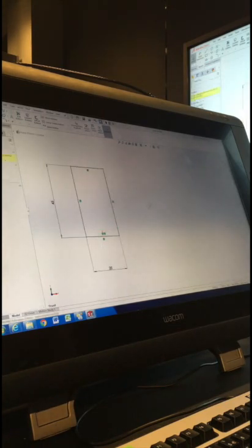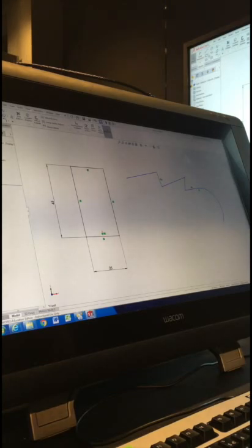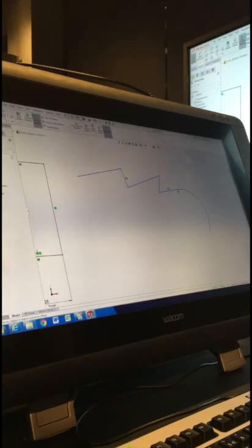Before we do the offset, I'm just going to explain to you how it works. The offset tool is on our sketch tools. See it up here, offset entities. Now by default, it'll be 10 millimeters with add dimensions and select chain turned on. I'm just going to turn them off. So how offset works is you put a dimension in, let's say 5, you select a line, and the preview will show that line offset 5 millimeters. Now you can select multiple lines, and if those lines are at a corner, they will trim those lines to match the same original shape.